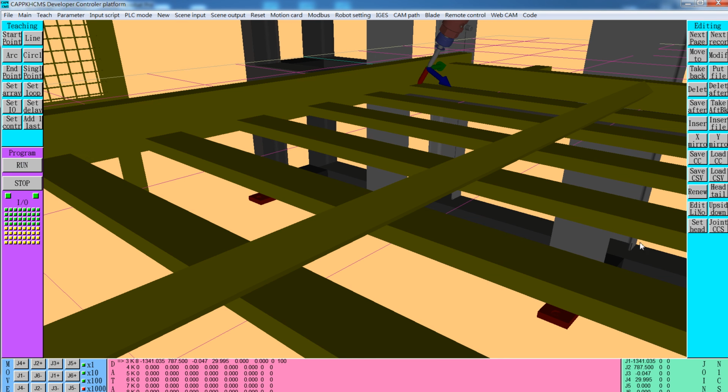It seems OK, and the head move to the first line, and insert one in front, and change to Cartesian coordinate system, and to let the tool locate vertically, use RY minus, press once, twice, 3 times. You can see RY equivalent to 90 degrees vertically.